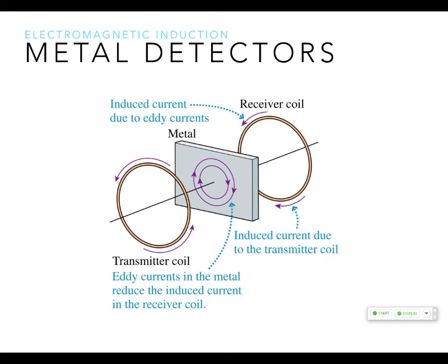If it's really noisy data, it can't identify which numbers it's reading, and it gives you an error. What the bag does is create a uniform spacing between the card and the card reader. If you have a gap and the card's in sideways a little bit, then these numbers are going to be detected differently than these numbers. So it creates an even spacing, and that gives you a better signal-to-noise ratio. If your card's not completely screwed up and still has some information that can be read, it's easier to read it. Yeah, that makes sense.